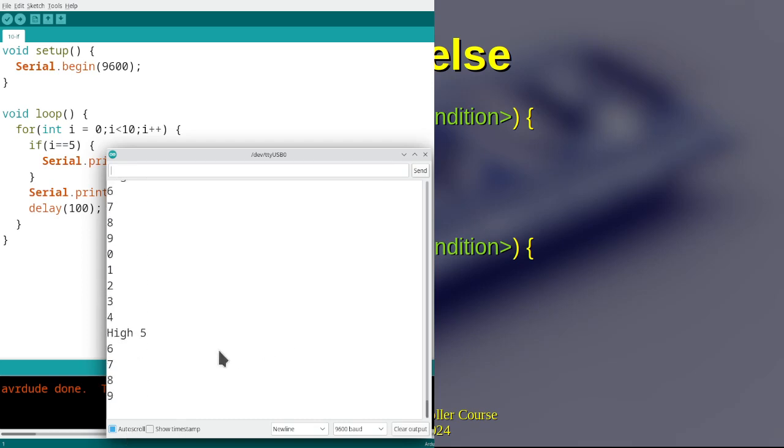Okay, so just a little tip here. If you want to stop this going by and freeze it, just switch off auto scroll. It carries on printing. You can see the position is moving here on that scroll bar, but we've frozen it so that we can see what's going on here, and then we can turn auto scroll back on, and it'll just carry on from the end. Just keep on scrolling as the data comes in.